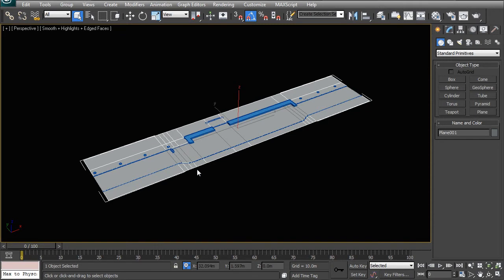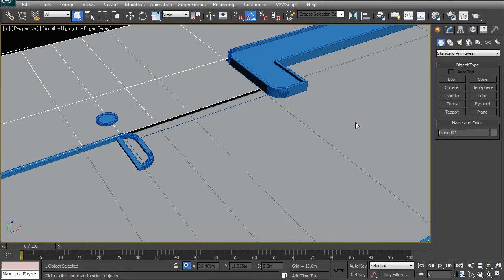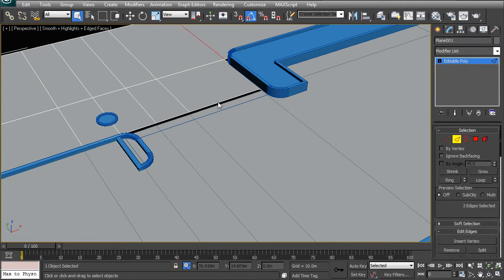So first of all, I want to just have a look at this edge here, which is quite glaring. We want to move these three edges down so that they meet the road, since this is the car entrance up into the parking. So we can move these three segments down by minus 0.15 meters, so it's half a foot.